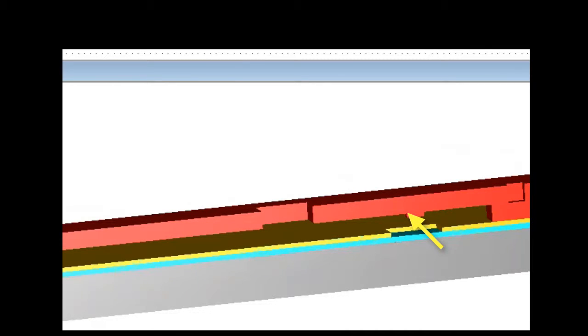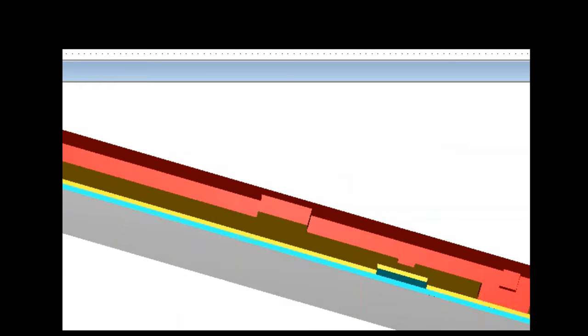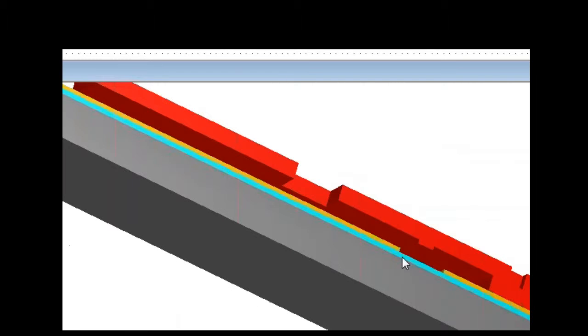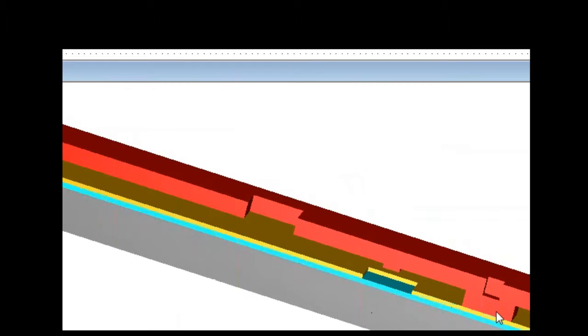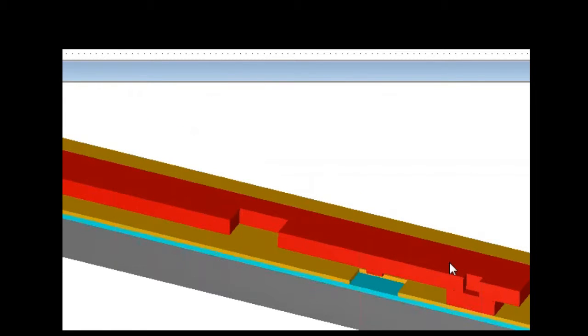That's because the polycrystalline silicon is conformal. So it follows the shape. And I'll probably do an iPad cartoon on that and post that so you understand how conformal deposition works. Okay, but that's where that comes from. And if I make a big enough anchor, you can see the dimple in there because it's filling this hole up. So some of the material goes down into the hole and leaves like a little divot on the top. So, if I'm layering something and I'm layering it into a hole, you'll see a divot going into it.